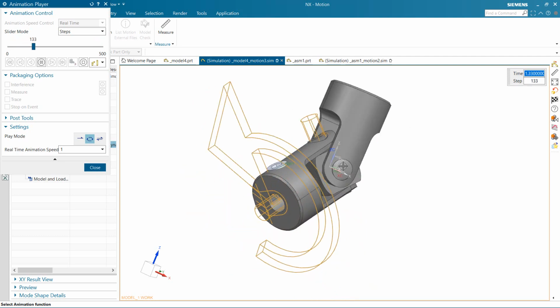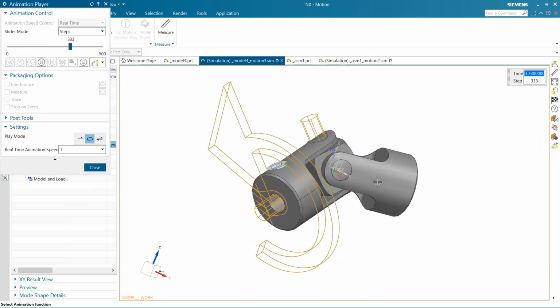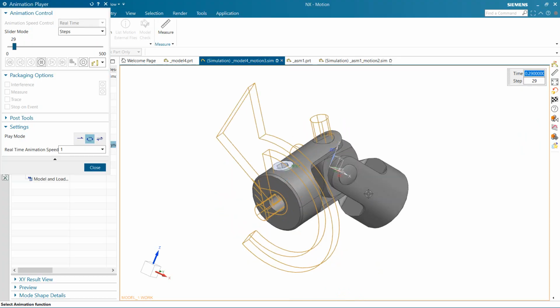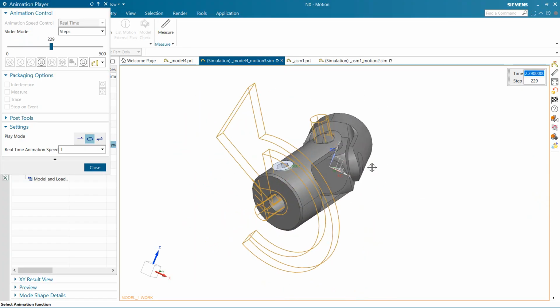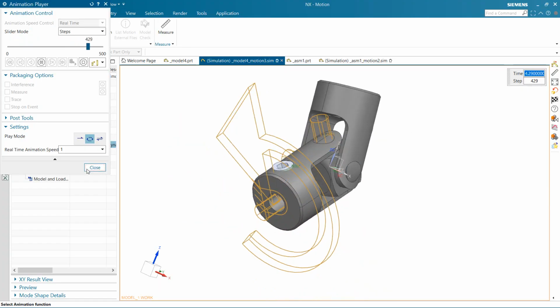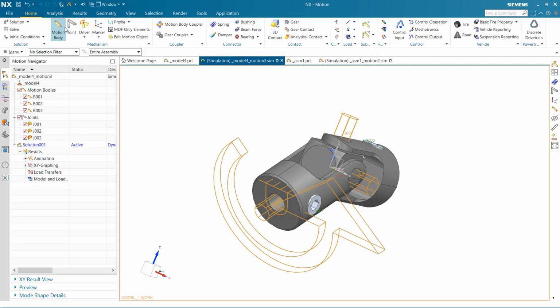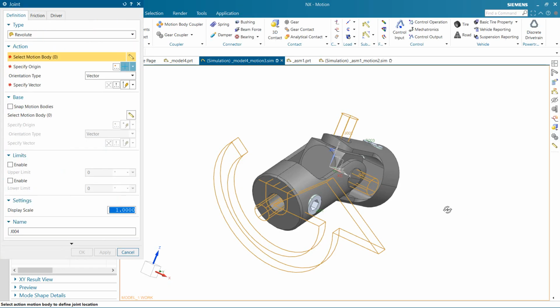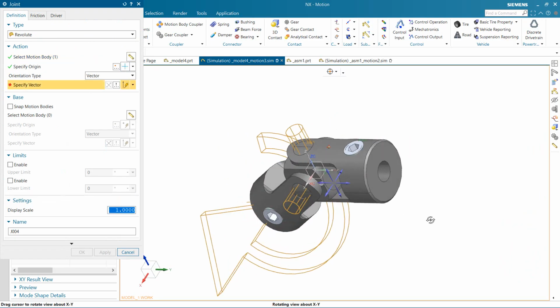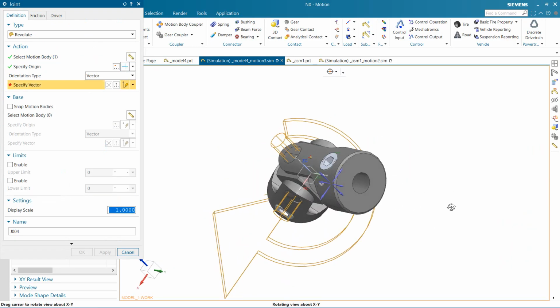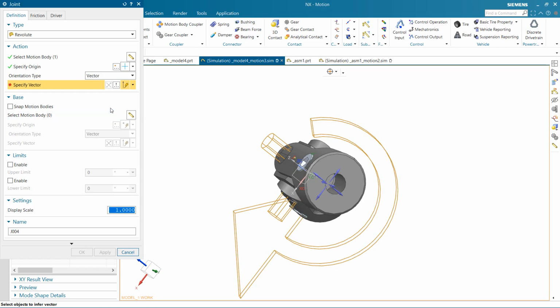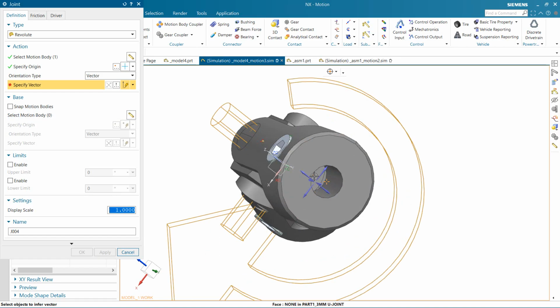So if we just let them fly like this, the design is definitely not going to be good, and the mechanism is out of place. So what we want to do here is create another joint for it. So, joint. We basically fix that. It can only rotate around here. If we do not choose the base body for it, it's just going to spin here.